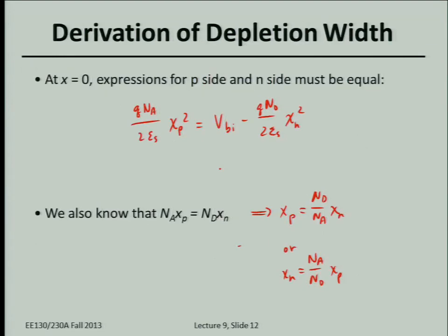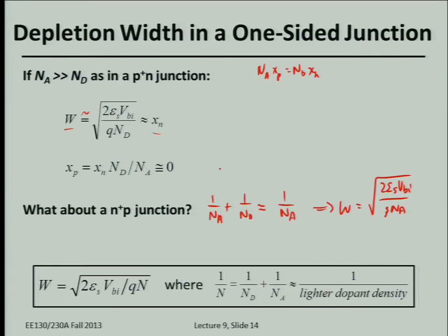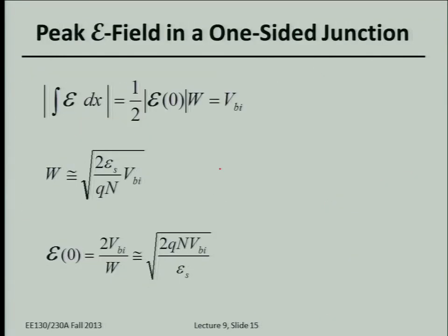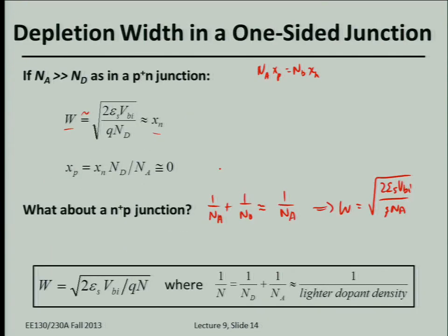Okay, so I don't know if we have an example, maybe not. Just order of magnitude, typically a depletion width depends on the doping, right? The doping can change over many orders of magnitude. In an integrated circuit, on the lightly doped side, it could be 10^15, 10^16, up to 10^18, mid 10^18. So it's orders of magnitude.